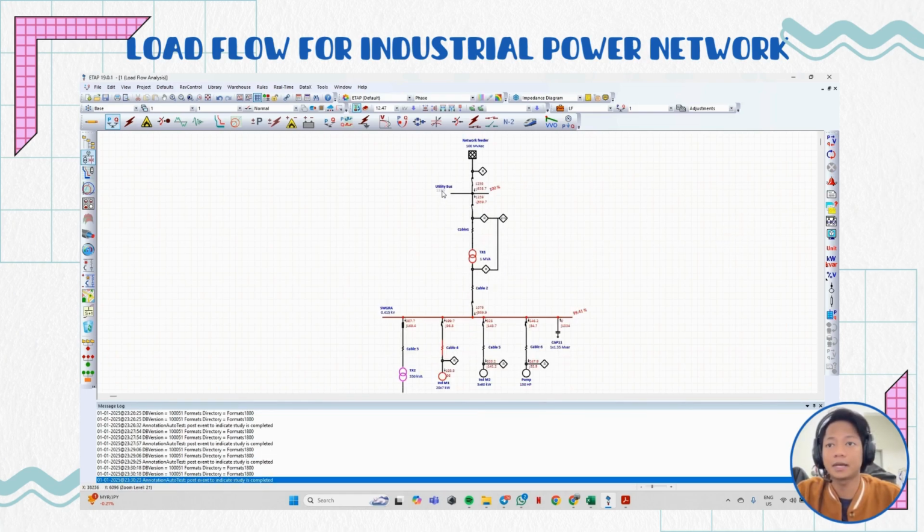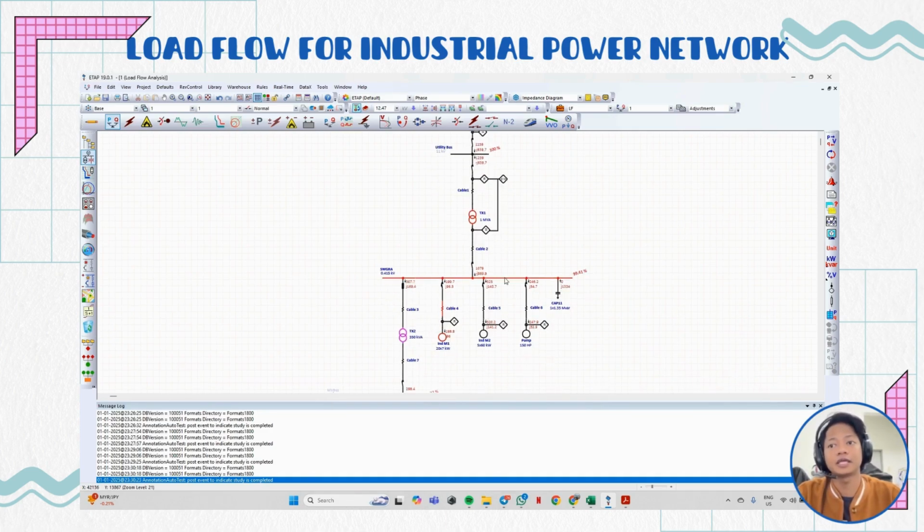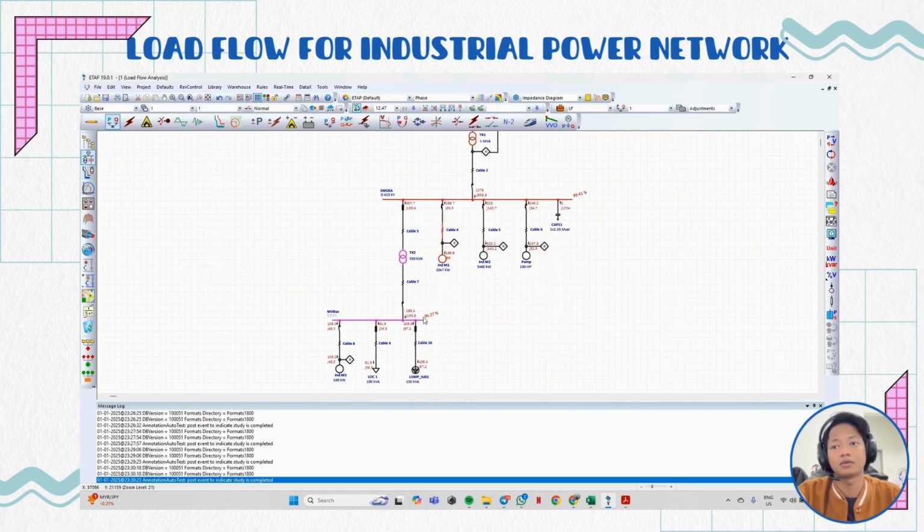For the utility bus the percentage voltage is still the same, but for the SWGRA the percentage voltage increased from 82.43% to 99.41%, and the MV bus also increased to 95.27%, from 72.92% before modification. So we can see that the percentage voltage is increased.